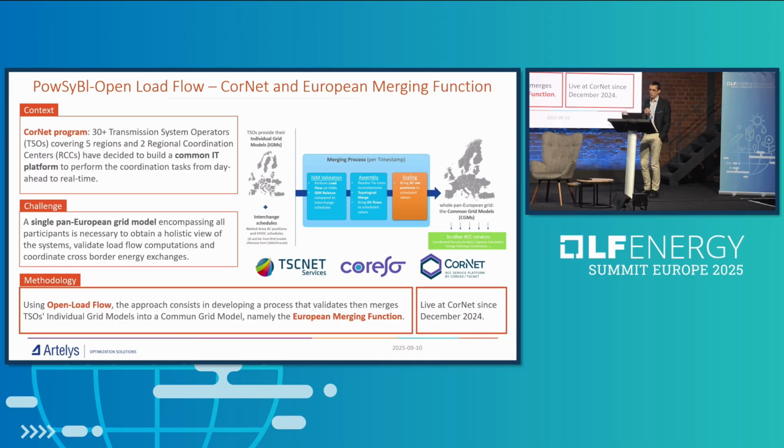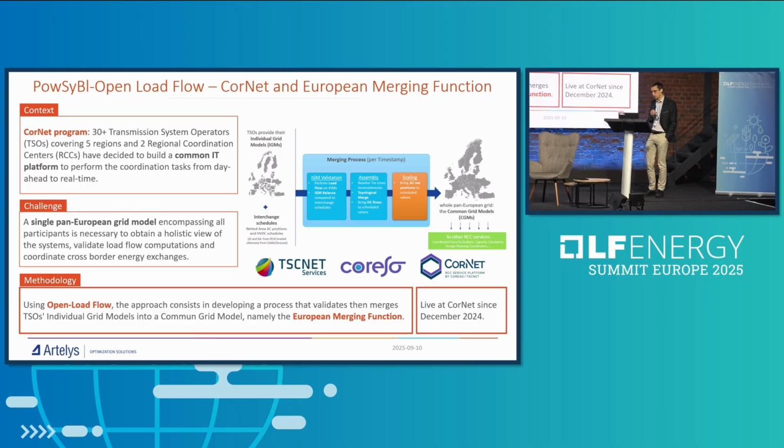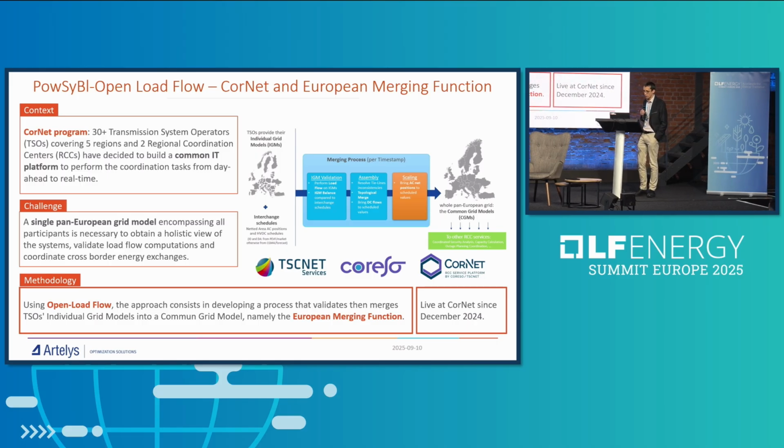The merging is basically rather simple. You receive individual grid models from all of Europe, from all TSOs, not only from the TSOs that are shareholders of TSCnet or CoReso, but from all TSOs. And then you merge them into a single grid model on which you can do European-wide computations like security analysis.